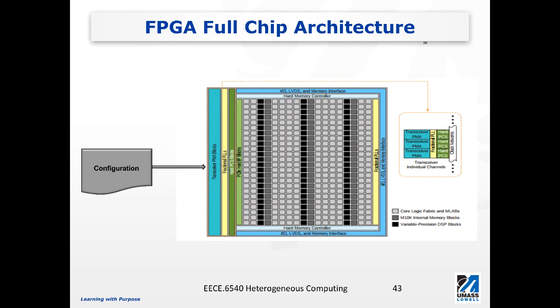This picture illustrates the important components inside an FPGA, including the logic blocks or logic elements, the interconnects, and also the DSP blocks. It also shows the transceivers and other I/O elements that are important to talk to other internal or external components.